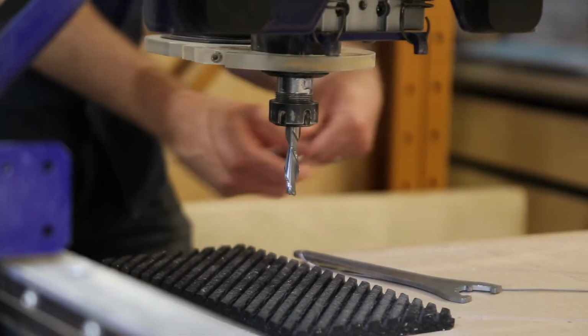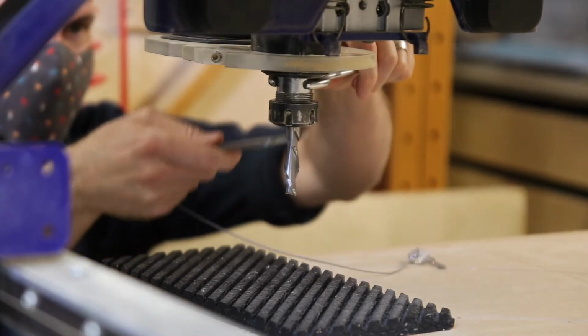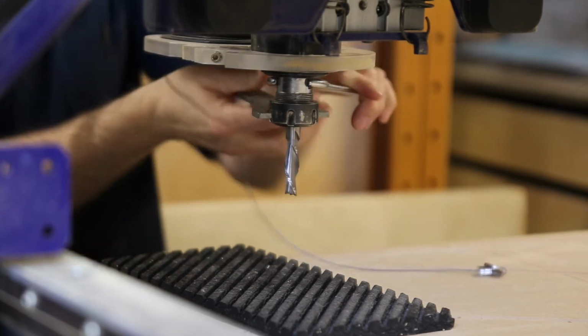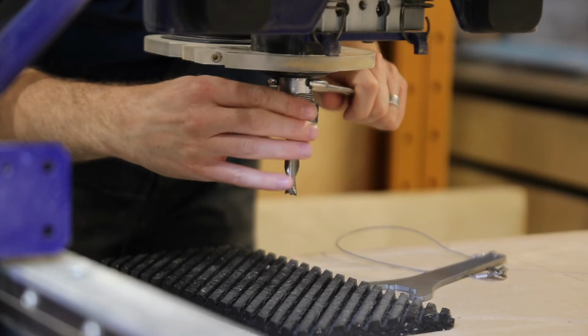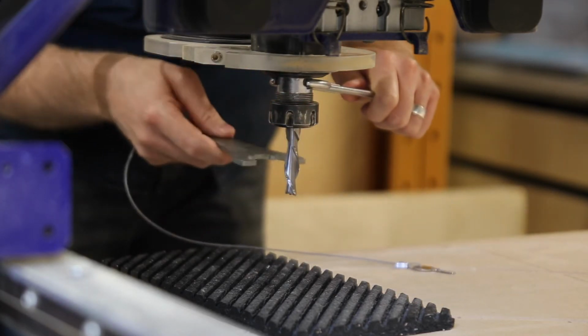If the machine has not been run that day or idle for more than 4 hours, you must run the spindle warm-up routine, which extends the life of the spindle bearings. Ensure that the collet and nut are not in the spindle. When removing bits, please use the rubber mat to prevent the carbide bits from breaking or chipping.